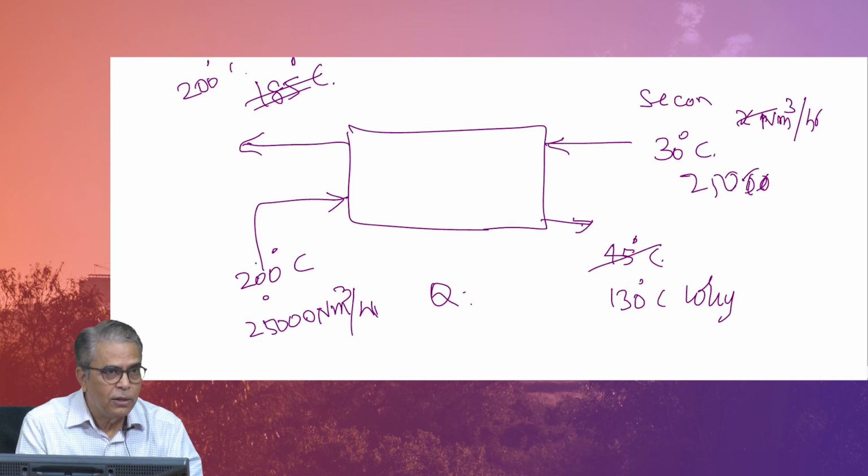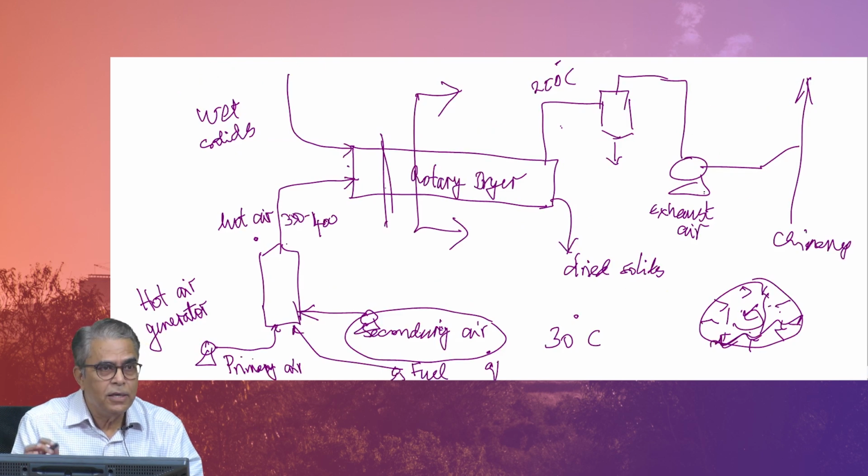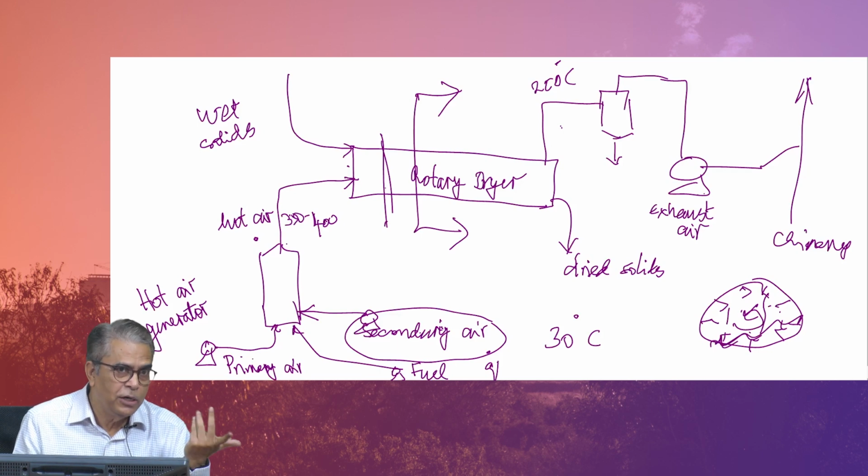So, with that, the next question is you have to check whether this existing fan is in a position to handle this extra pressure drop. If so, you are lucky, you got away, no need of a new equipment. If not, you are stuck.